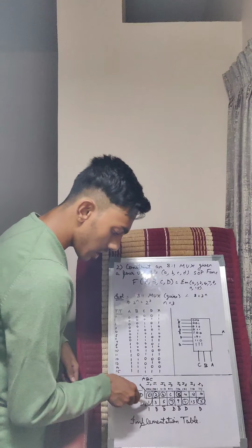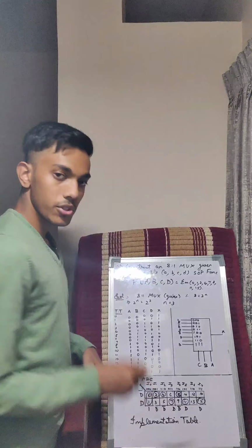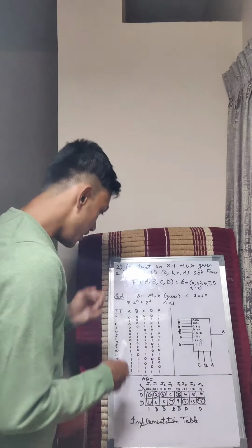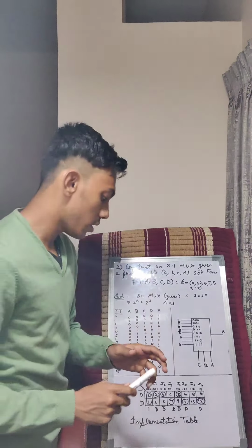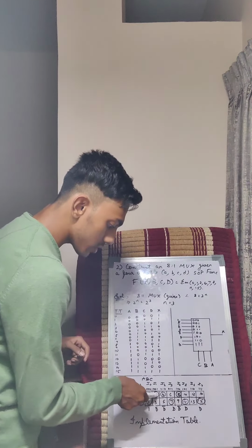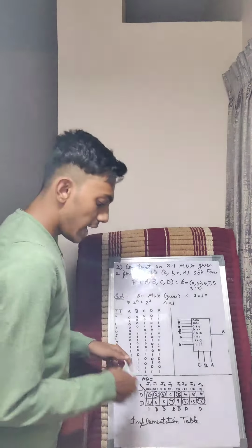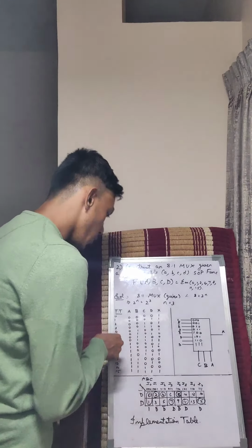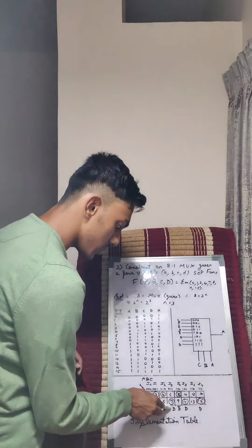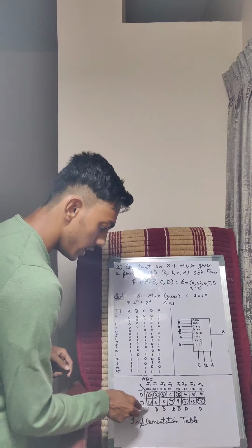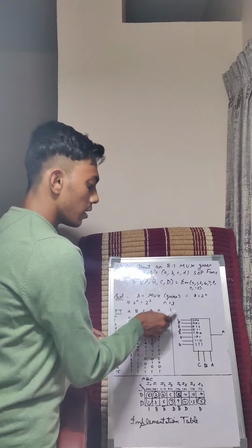Now when this portion is circled entirely, its equivalent is supposed to be 1. Now look at 2 here, there is 1 here. I'll circle that. But 3 is 0, so you don't have to circle it. Here it is only 2. So what is the corresponding D here? It's supposed to be D bar. So you write down D here. And this goes on. When it is 4, it is again D bar. When it is 7, look at this. This is 7 here. What is it corresponding to? It's corresponding to D. Once you've finished writing down all this, you can construct the multiplexer here.